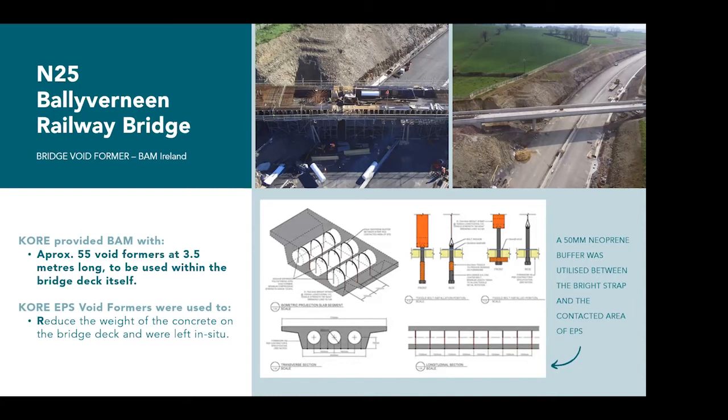So vastly reduced weight of concrete. So the structure was able to work that little bit easier for them. Reduce the weight on the bridge deck. And because it was an EPS, because it's going to be left in situ, they knew the long-term performance of the EPS, and EPS has been on the market in its current form for 70 years. So it is around a long time, and it is a proven material. So that project was very, very successful for them.